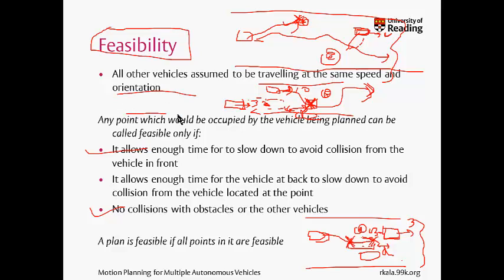What in general we observe is that if I am moving out here, I never make a lane change if there is a very fast moving vehicle out here. I know that this vehicle will not be able to slow down. So before making any lane change, we make sure there is no fast moving vehicle very near behind. And that was the problem with this scenario. The 10 mile per hour vehicle did plan to overtake the obstacle and did think that it would not collide with this vehicle, but because it had to terminate its plan, suddenly a collision happened.